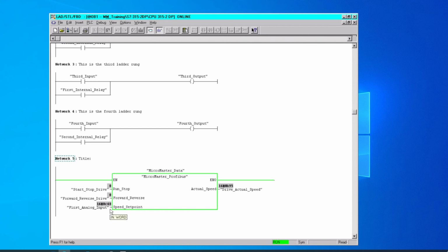So again, when you go to that window menu and look at all the blocks that you have open in the ladder editor, the one that has the @ sign in front of its listing in that window menu is the one that currently is being monitored, and that's where we need to go to turn off the monitoring or the eyeglasses in that block.